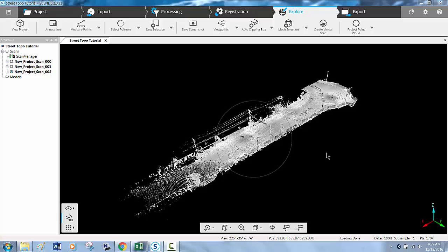Okay, so this is going to be a video going through some of the features of Scene, such as georeferencing a point cloud, creating a heat map on concrete, locating and getting some coordinates of rebar, and then running an FF test on the concrete.